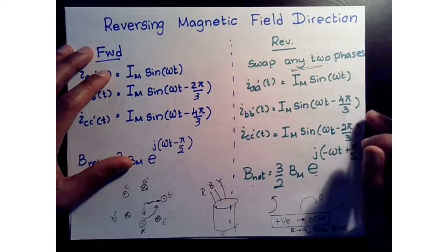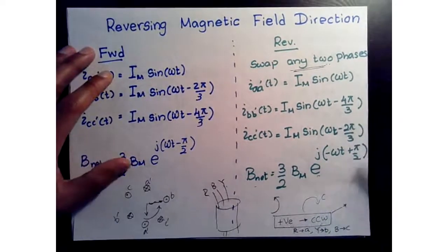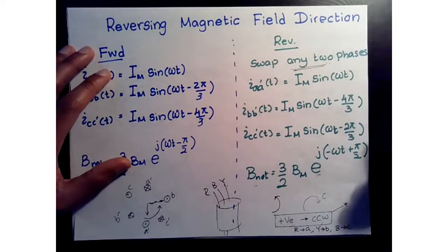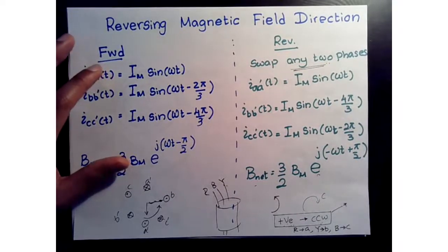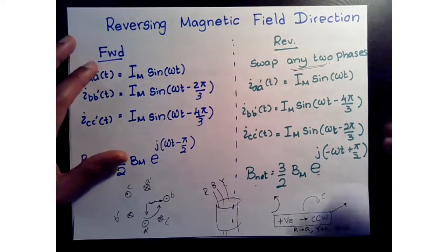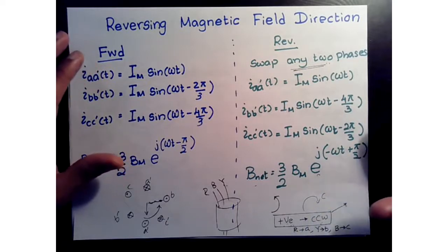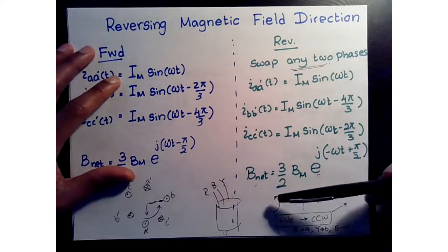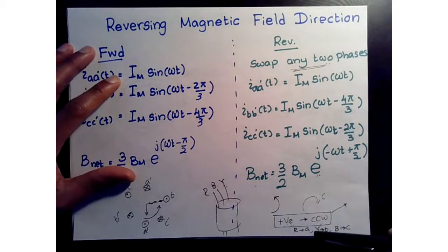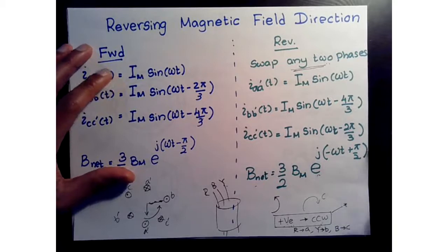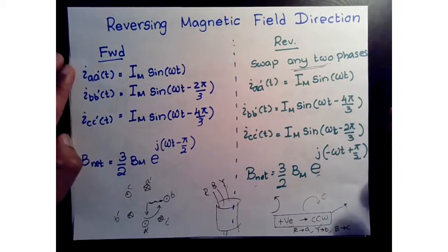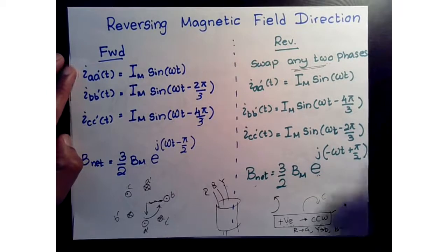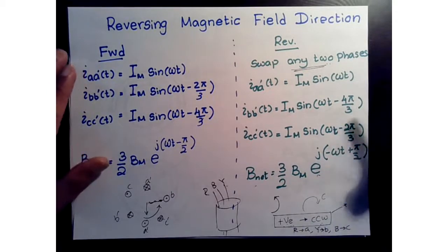This also is important in setting up a machine for the first time, when you have to couple it into certain hardware. When a motor designer designs a motor, there is a certain polarity they call the positive direction, and for that positive direction they will specify a certain phase sequence. So as you get a motor, in order to determine what that positive direction is, that's something that you have to determine.